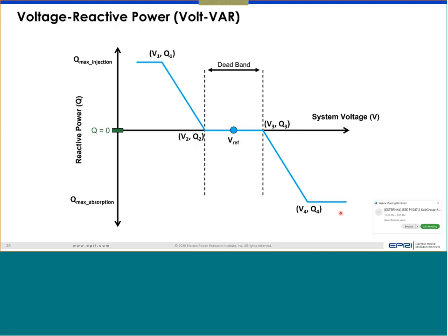So there is a lot of flexibility in the definition of the Volt-VAR curve, and by using a pair of points, it's easy to configure those definitions. Now, what do we mean by autonomous? As a utility, you first have to activate the Volt-VAR function, then it has to have a profile like this, that relationship or Volt-VAR characteristic.